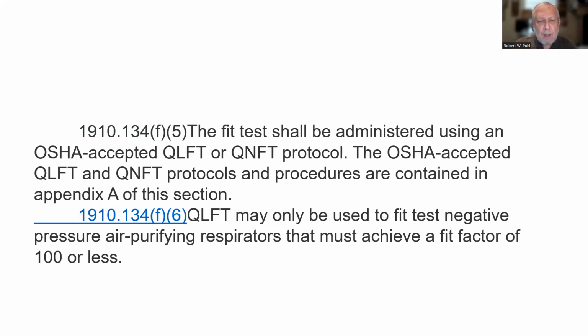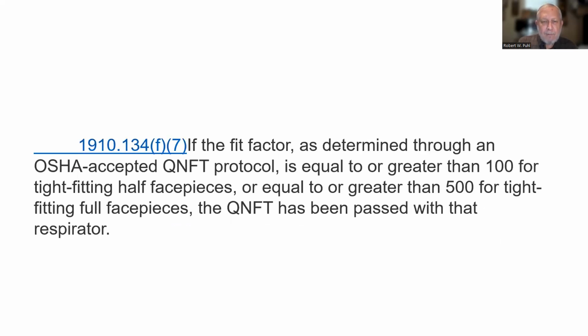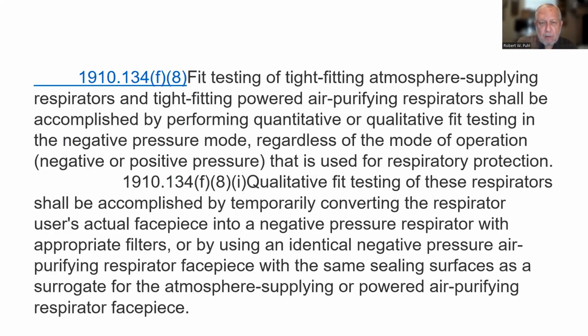1910 F6 QLFT may only be used to fit test negative pressure air purifying respirators that must achieve a fit factor of 100 or less. If the fit factor as determined through an OSHA accepted QNFT protocol is equal to or greater than 100 for tight fitting half face pieces, or equal to or greater than 500 for tight fitting full face pieces, the QNFT has been passed with that respirator. In other words, you got to use that respirator then.